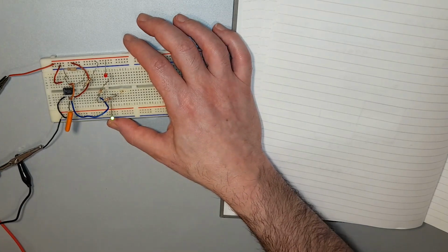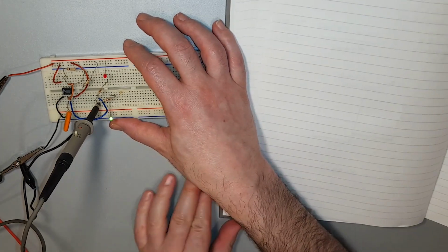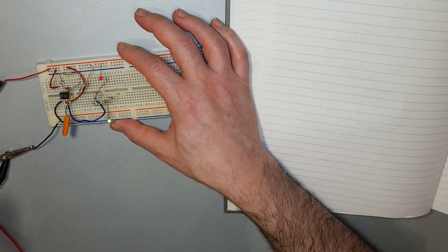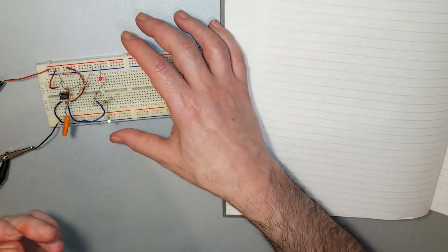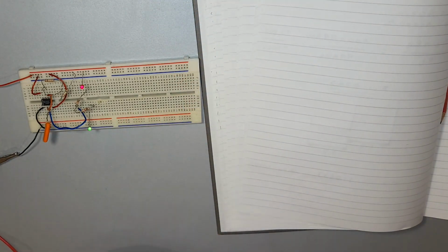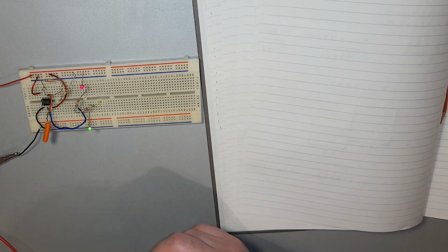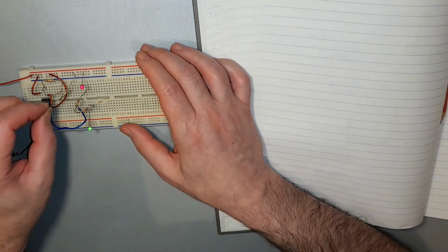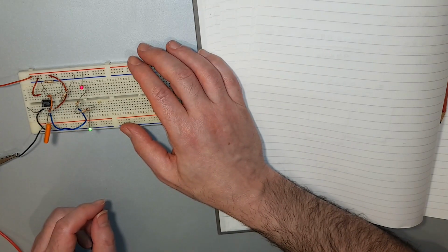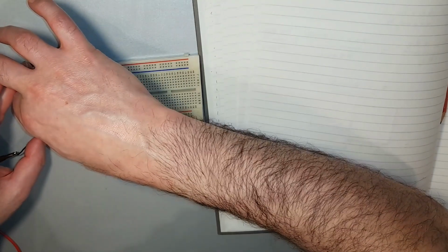Right, so let's look at the mark to space ratio on that. And it's about a 2-to-1 duty cycle. Okay. And now hopefully this diode, which goes from the junction of the 2 resistors and that diode with its anode go in here, and then its cathode going to pins 6 and 2, which is over here.